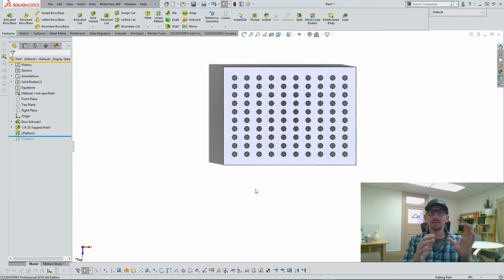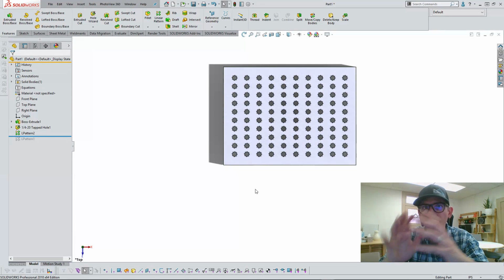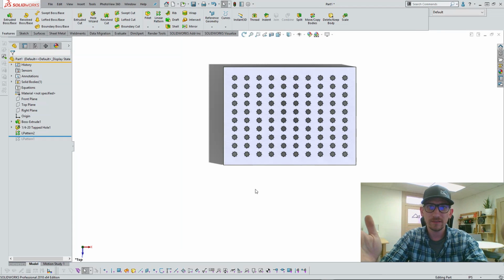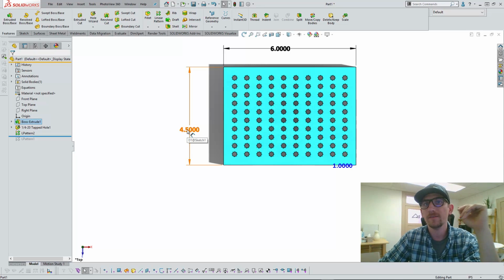Now here's where this gets even cooler. I love using the term, let SOLIDWORKS model for you, don't model for SOLIDWORKS. Some of the parameters that I mean by that is I like creating SOLIDWORKS models and having pre-existing geometry control new geometry. One way we could look at that is in this linear pattern up to reference function. So let's say you design this plate with all these tapped holes in it, and you're looking at it, but now you're going, oh shoot, that 4.5 dimension is not correct. I needed that to actually be 5 inches.